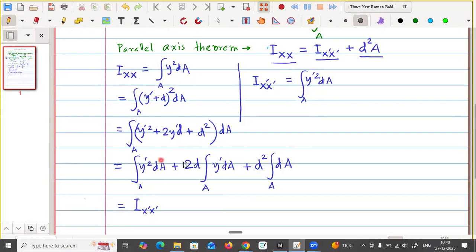Okay. So in some books, you will find that it is simply x. Okay. As a quantity, this is all right because this is about x-axis. But when we consider this as a tensor, then in that case, mentioning both the indices is important because it can be a product of inertia, and in that case, it will be x, y, etc. But in your case, product of inertia may not be that important. So simply understand that. Okay, that is why we are writing it twice. So actually that is a physical quantity and that has some relevance. That is why we are writing it twice.